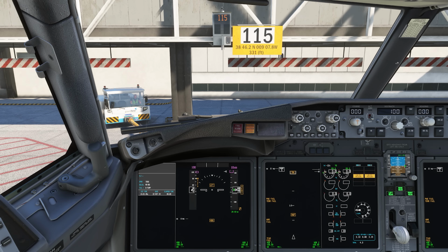So we briefly covered the engines outside. We talked about the fan diameter. We'll go in a little bit more detail about these LEAP 1B engines. So at my operator we have a 27k thrust rating, and the derates are no longer 24k and 22k. They are 10% less and 20% less thrust than rated thrust.